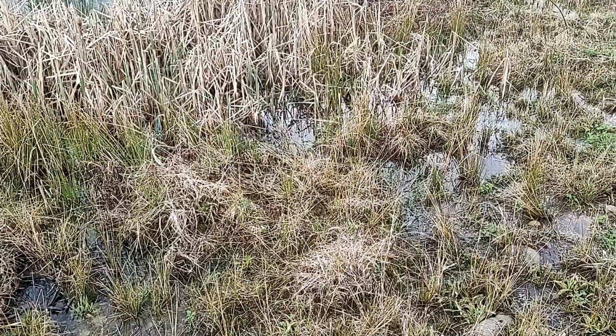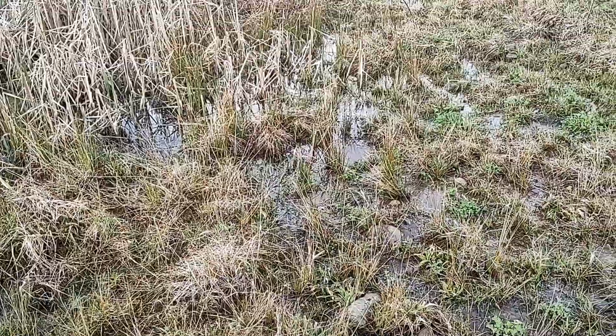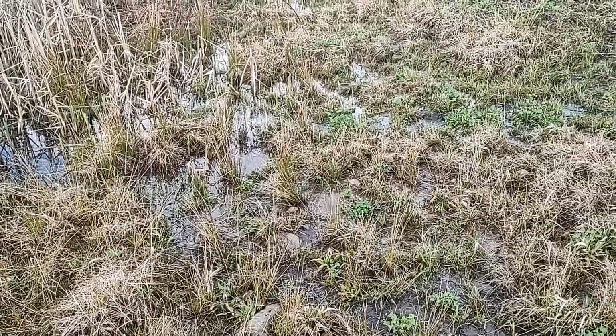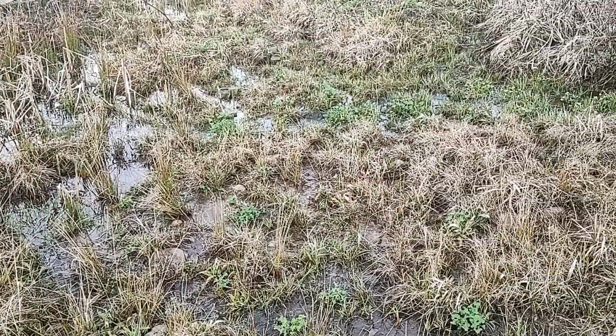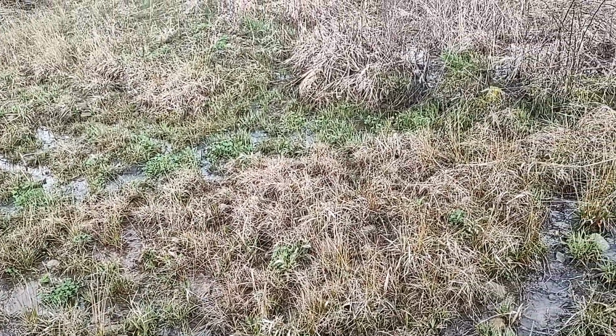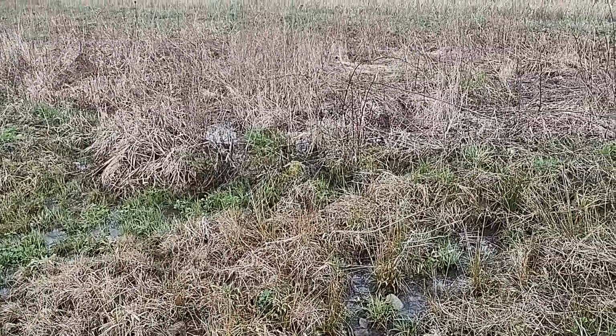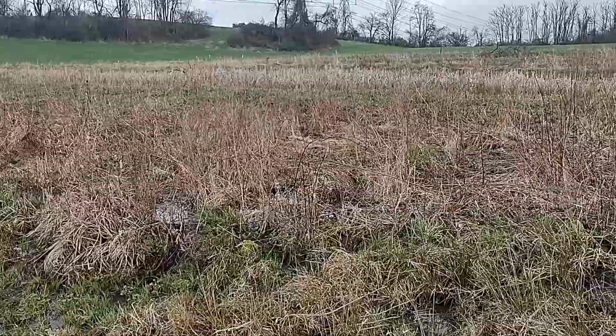Look how the water flows in a sheet-like pattern without causing erosion over the entire surface of the spillway that we constructed for a wetland in New York. The spillway connects two newly restored wetlands and was built to carry water on a slope of only 1%. There was no need to armor the spillway with rock. The spillway has become a wet meadow wetland.